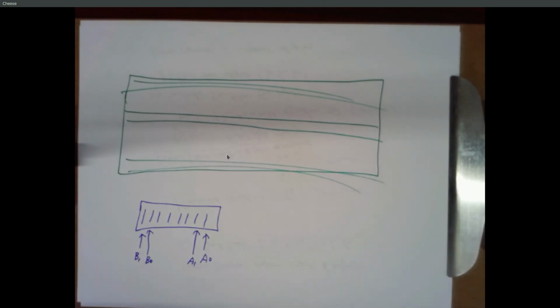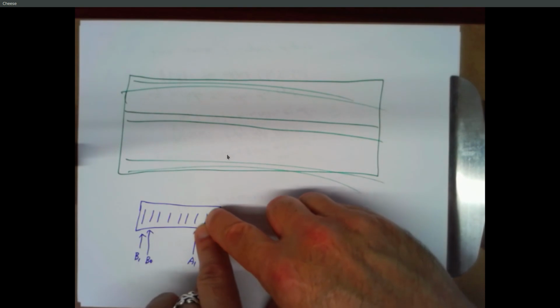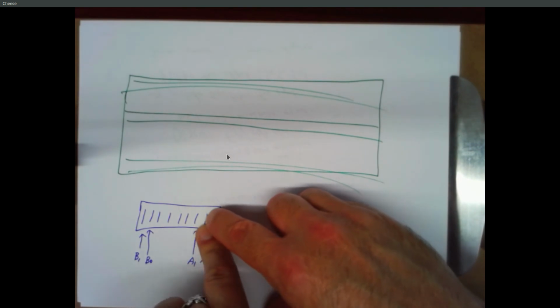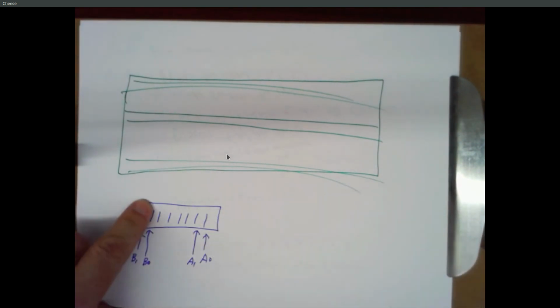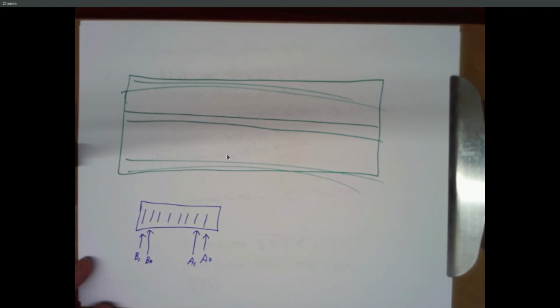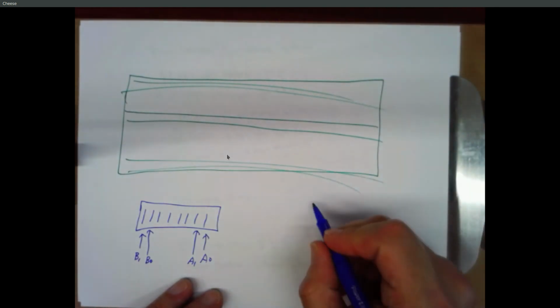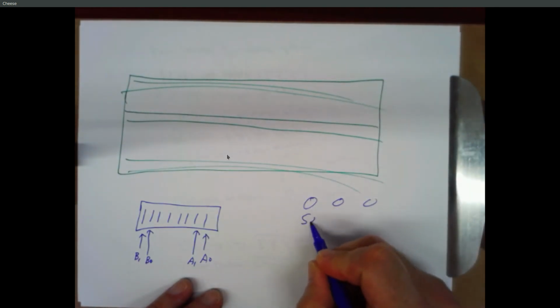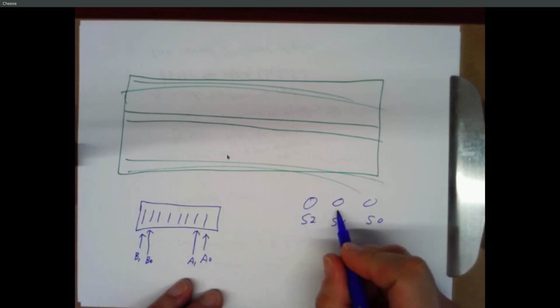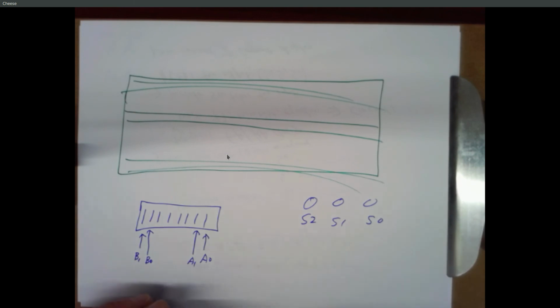And if you're demonstrating your circuit to me, I'm going to insist that that's how it works. So if I want to do 2 plus 3, for a 3, I would turn both of these switches to whatever position represents a 1, and I'd turn this to be a 1 and a 0. And on your LEDs, somewhere in your proto board, you're going to have 3 LEDs. Wherever you put those, put the most significant bit on the left, and then the next bit, and the least significant bit on the right.